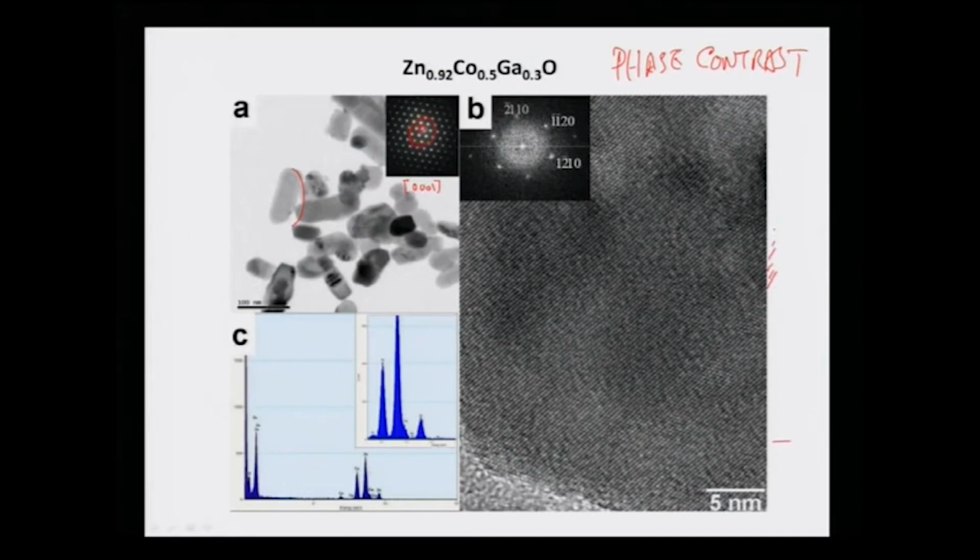Not only that, one can actually take this real space atomic arrangement image and do Fourier transformation using different kinds of software which are available in the market, and then one can easily get back the diffraction pattern which we obtained in a normal electron microscope. So, this can be used to show that whatever image is formed using the phase contrast mechanism reflects the real space information.